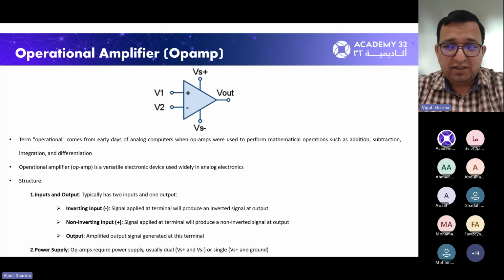But if there are other requirements, for example if you want to control the biasing of an op-amp, or put in some special switching circuit to change the gain or switch the gain of an op-amp from one configuration to another, or to change the compensation of an op-amp, then some extra pins might be available. But generally, these are the 5 basic fundamental pins available in any op-amp circuit.